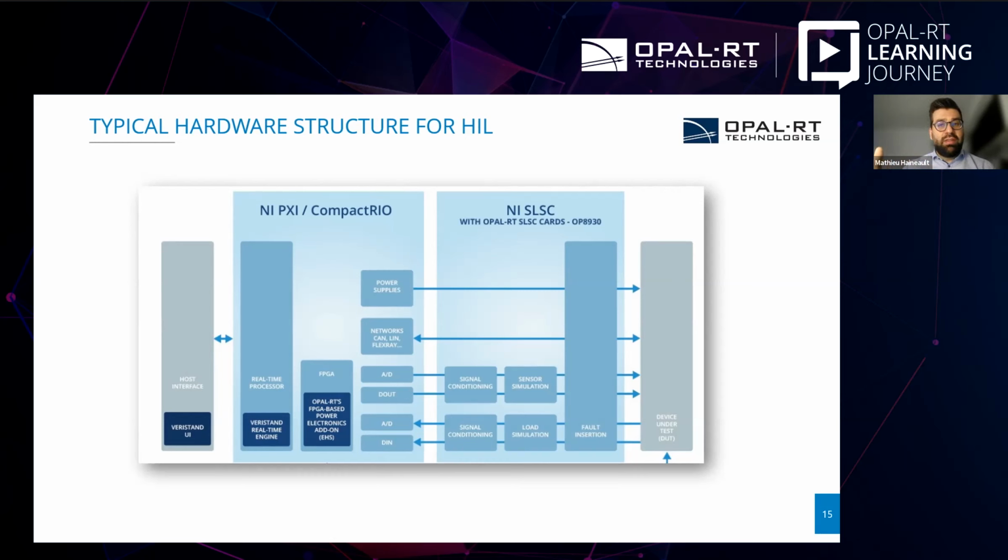NI and OPAL-RT have developed an SLSC board. The SLSC is really a conditioning unit. Any IOs or communication can pass through the SLSC and be adapted. What we bring here usually is fault injection capability. You have resolvers, with your sine and cosine. We pass the sine and cosine signals through the SLSC cabinet, chassis actually, and you can apply real faults, like open signals, like losing one signal, to the device under test that you're testing.